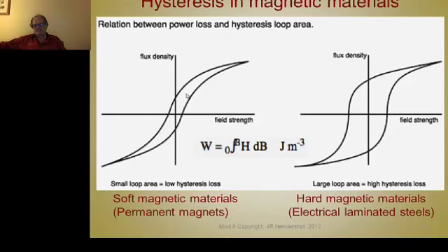We want the flux to be adjusted in there from the coils that are in the stator. Then we want this to be zero. We'd like this to go through zero or as close to it as possible. So this is a hysteresis loop of a soft material, not a very good soft material. It's got too much residual magnetism.